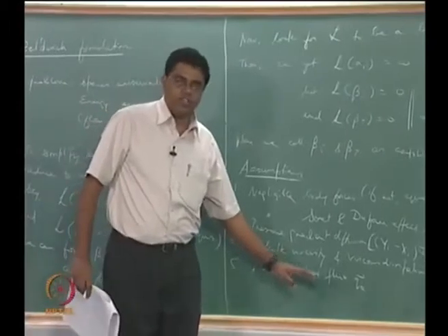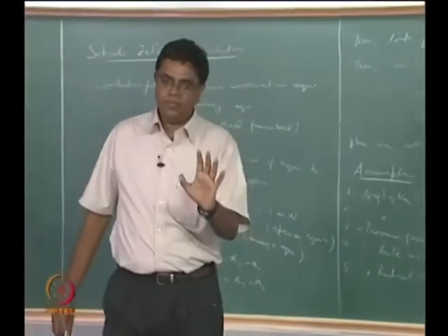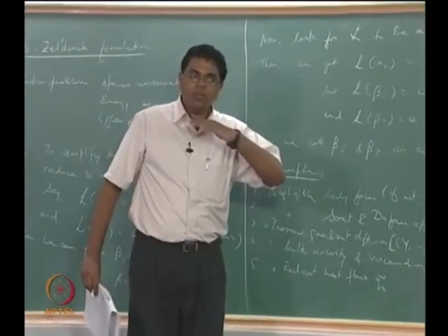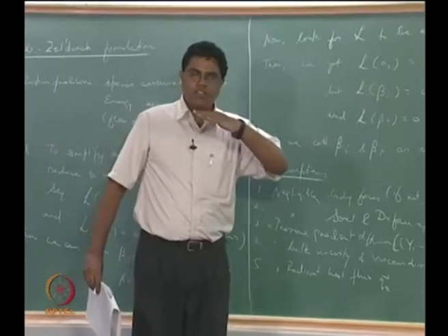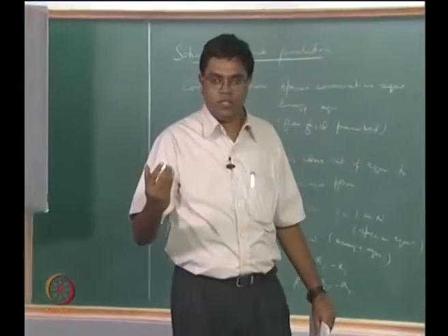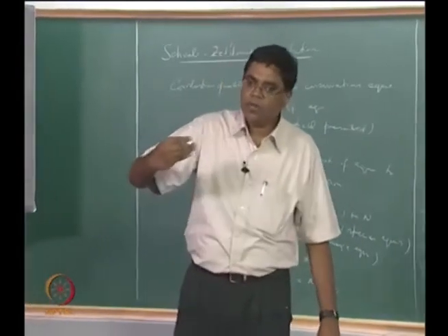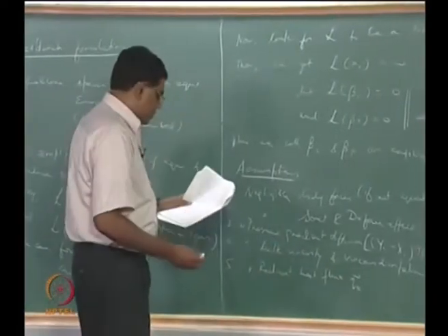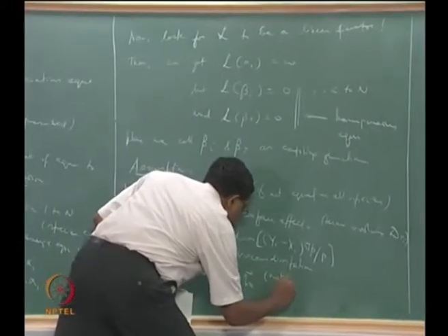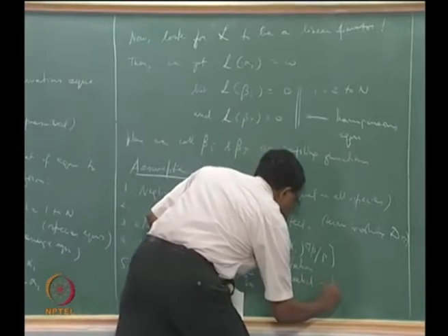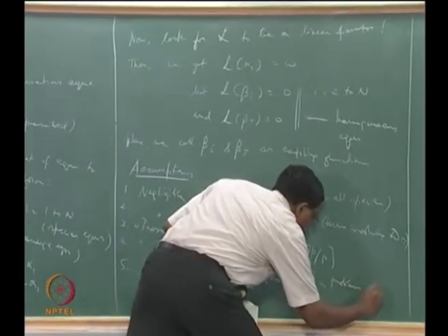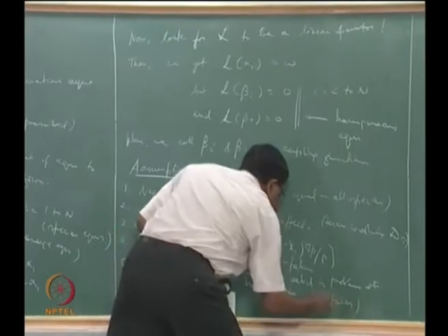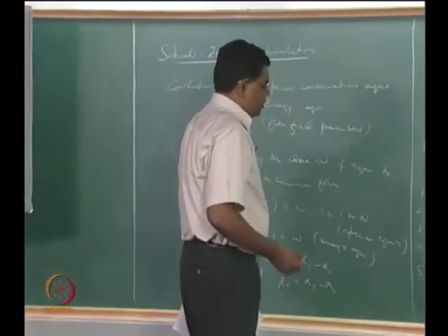But of course when can you say this is okay? So long as you are dealing with a gaseous medium, this is reasonable, okay. But the moment you have things like surfaces, you have to think a little bit harder. If you have surfaces, you have to look for whether those surfaces are transparent or opaque, or if they are closer to black, if their emissivities are closer to black body emissivities, right. So if that is the case, then you can't neglect this. So not valid in problems with phase interfaces.